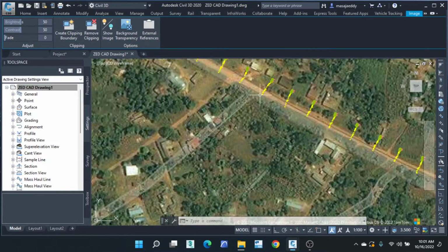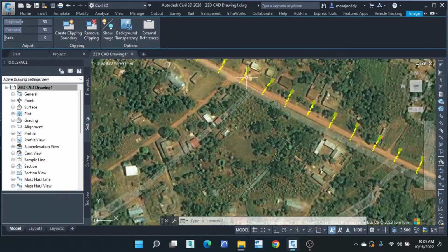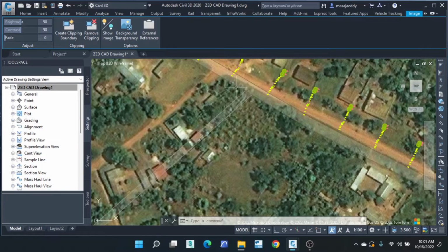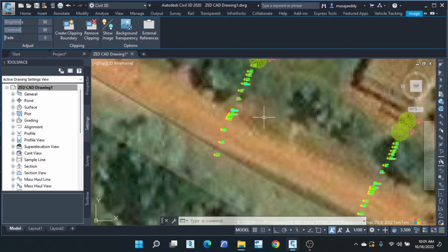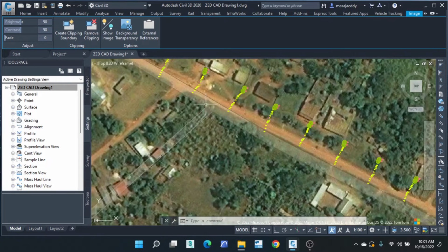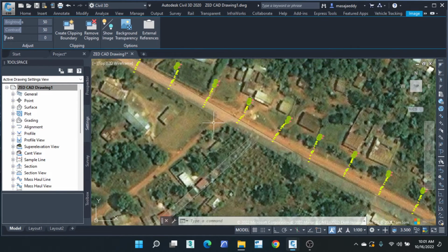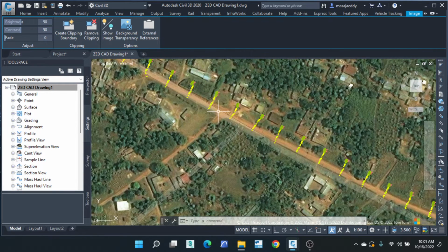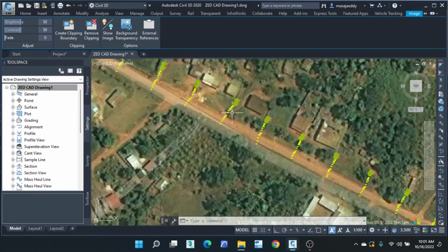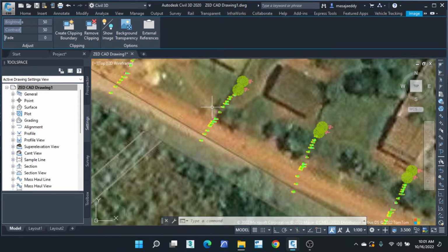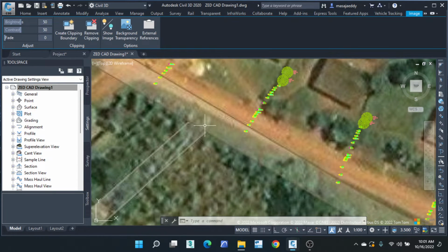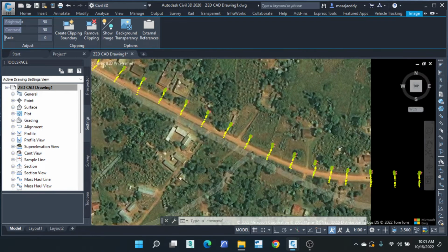As you can see with the images, there's a little bit of displacement from here, right? This hybrid shows that this is actually where the road is. Now the person that picked also shows a different point. Yeah, these ones also, the surveyors usually pick the actual one, but as you can see, there is always displacement within the satellite views.